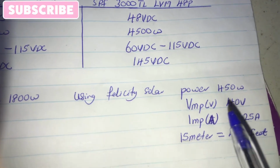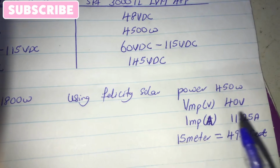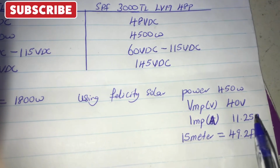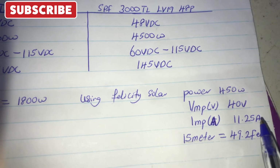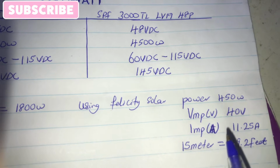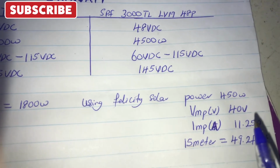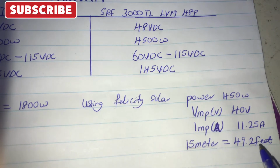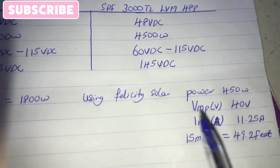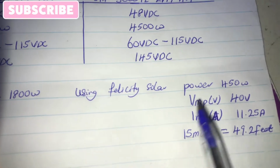So this is the highest voltage it can bring out, which is 40 volts, and the highest amperage too is 11.25. This is not the short circuit amperage. I think the short circuit amperage is 11.9, and the open circuit voltage is 47 volts, but that's not what we are using in this calculation.